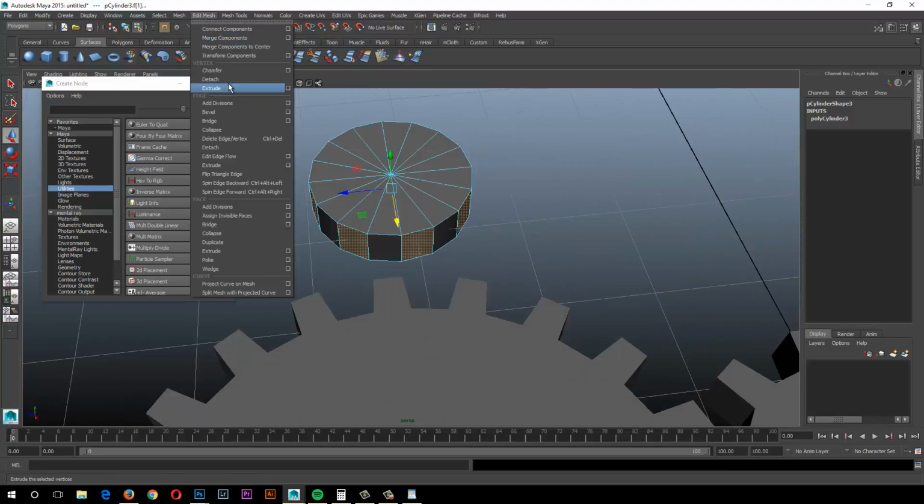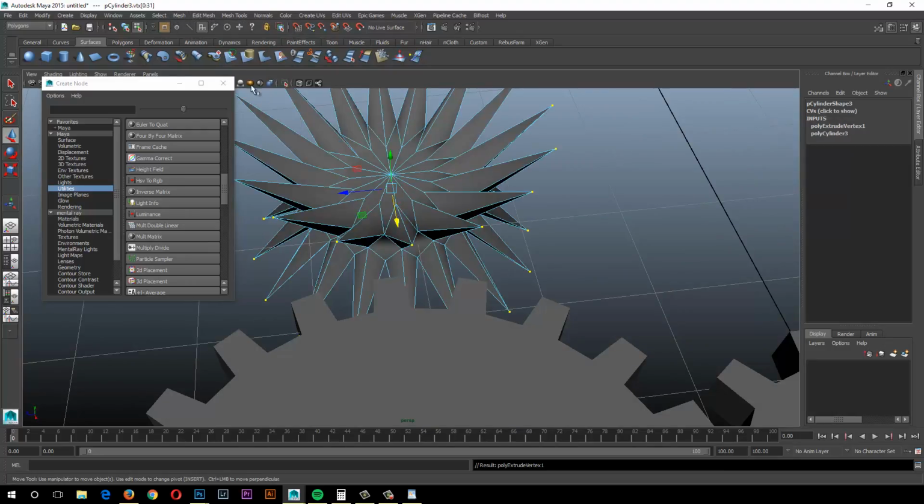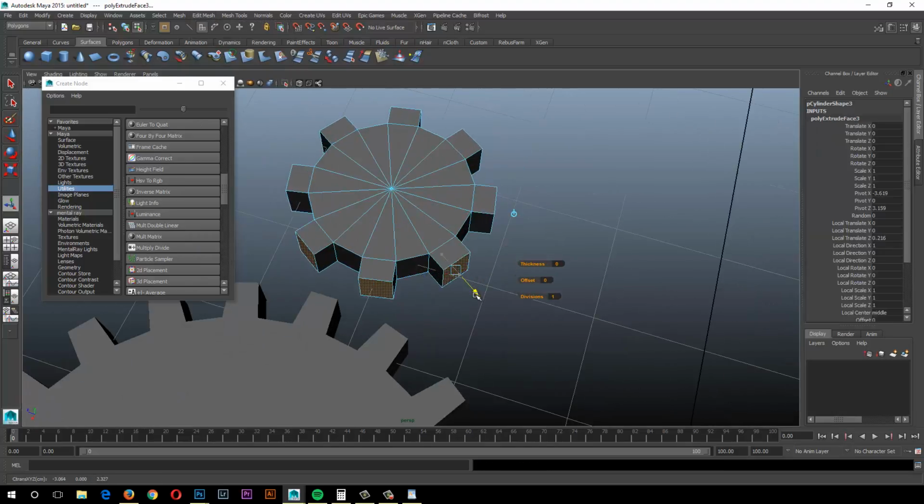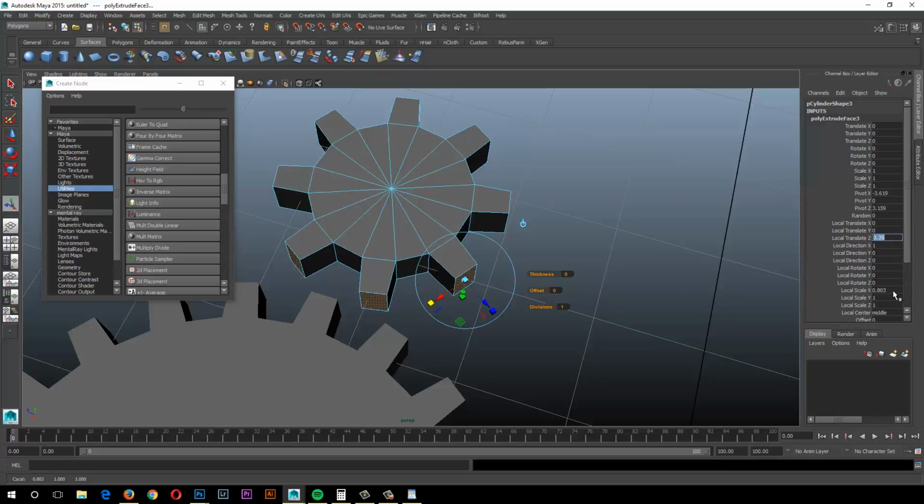And mesh, extrude. Oh, yep, did the wrong one that time. I did vertex edge. So face, extrude. And again, just hand doing those so I can see which numbers to type in quickly. 0.35 was the value. And again, you can use whatever value you want. They just need to be the same. I'm guessing if they get too long, then they probably can't rotate into each other easily.